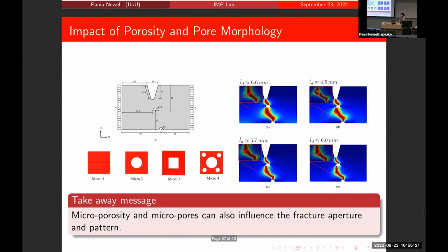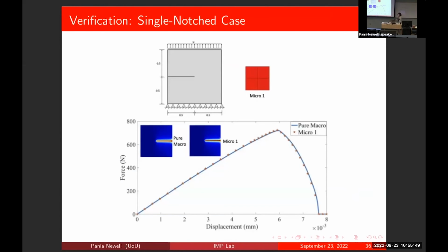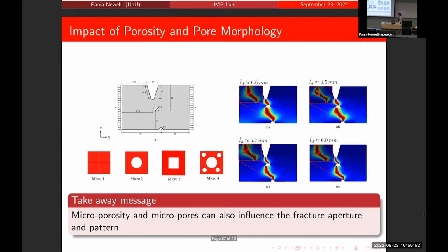So in that case, how is the porosity included in the phase field? The porosity is not included in the phase field. Remember that when we do the homogenization, the porosity comes through the homogenization and then the properties. The phase field is right at the continuum scale, but it sees the impact of the porosity. Those are basically coming through the homogenization. Oh, I see, so you have the homogenized energies. Yes, and the effect of homogenizing across different types of porosity is reflected in this matrix. Yeah.